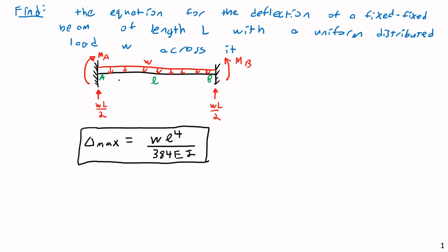Well, in that case, symmetry goes right out the window, and we would have to solve everything for three levels of redundancy. That means three redundant beams. That means you would have maybe an ABC, and you'd have theta AA, theta AB, theta AC, all down the line. You'd end up having nine lowercase thetas, and you'd have to run a whole bunch of balancing, and it would be all sorts of fun.